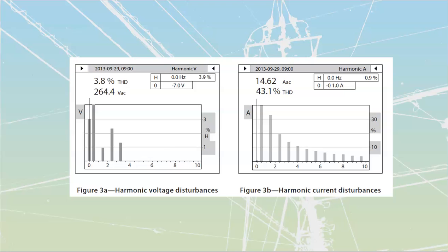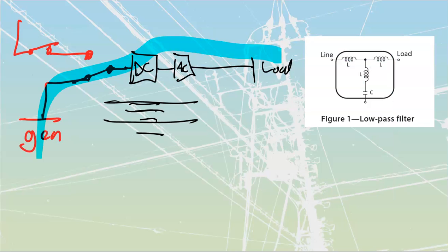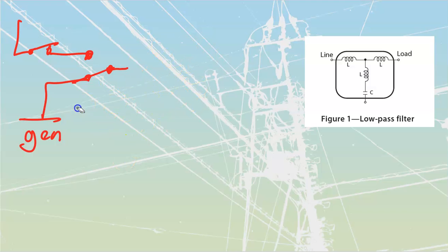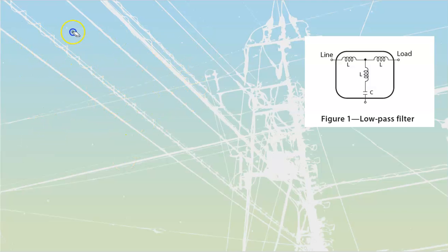Isolation transformers are very commonly used just as part of our power distribution system. The beautiful thing is that they also provide a little bit of filtering. Our most common type of transformer that we are going to see is where we have that delta primary and that Y secondary, which inherently does deal with a little bit of filtering for us. Some harmonic attenuation happens just off of that 30-degree phase shift. We also are not going to have triplen harmonics that get trapped on there. They're just going to get dissipated. They don't pass through, but they don't get stuck inside of there to form reflected wave systems or anything like that.